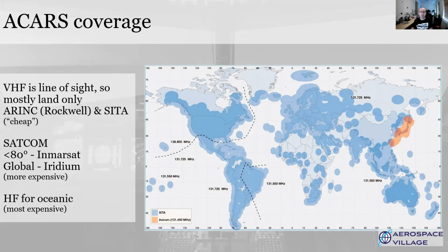Running all of these transmitters and maintaining the communications links between them is pretty expensive. Satellite coverage is also dependent on where you are in the world, although to a lesser degree. Inmarsat have coverage between plus and minus 80 degrees latitude, although Iridium have more lower satellites and can offer polar coverage too. There are only 15 high-frequency transmitters in the world, but they have long reach and are located for polar and oceanic coverage. The costs are a bit opaque, but one Asian carrier was paying the equivalent of $1,000 per megabyte on their HF service. That's still not home broadband prices though, and there is a bit of an old adage in that for aviation, you add another zero onto the end of what seems a reasonable price for anything.